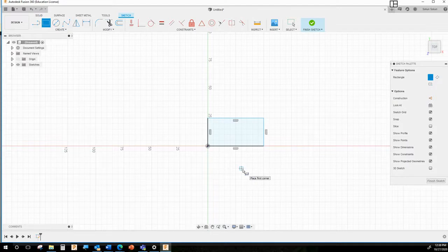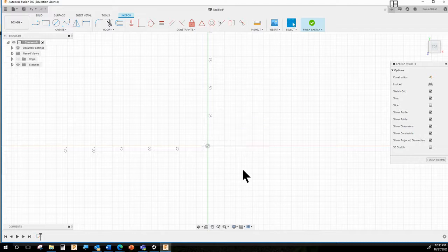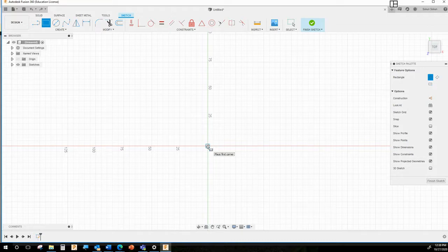And it's actually considered to be unconstrained, undefined. So it's this light blue, and it's just a bad thing. I don't know, this is for freehand sketching, is the idea, but I'm never going to ask you to do that. So you will never do that. So when you are drawing your rectangle, and anything you draw, you need to hold your mouse button down while you draw, or it won't act the way I'm telling you it should act, and you'll be really frustrated.